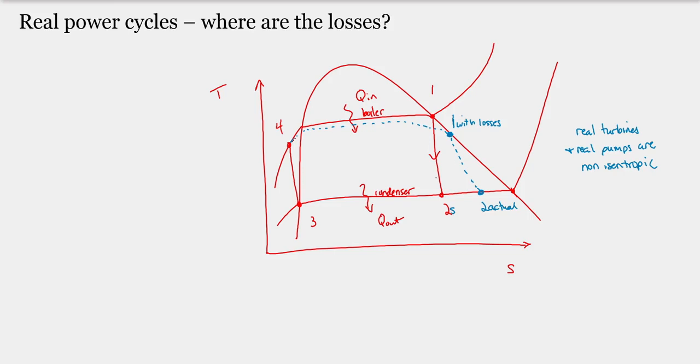What we would do is compare the device performance. We will circle back to this, but it's going to take us a little bit of time to get there. We talked about ideal cycle performance and how we use the Carnot cycle to define that. Device performance is also defined by the second law, as we mentioned a couple of segments ago. What we would do is compare the work out of these two processes, the isentropic process and the actual process, and we would define that as the device efficiency. Just so you have a reference and some foreshadowing for where we're going, turbines are typically 80-90% efficient. In terms of isentropic efficiencies, they're pretty decent. If you have a lower performer, it might be in the 70 percentile.